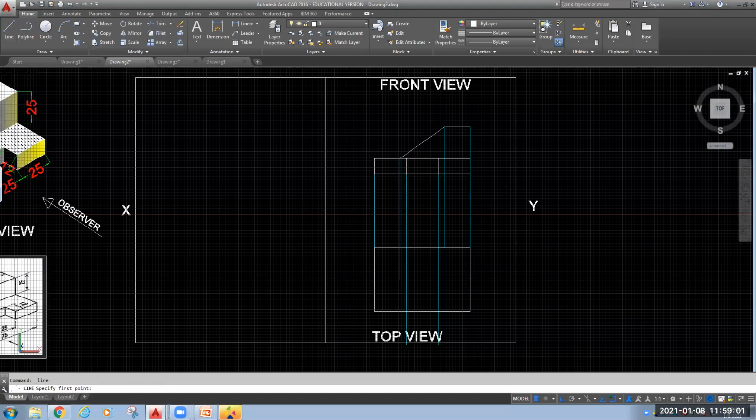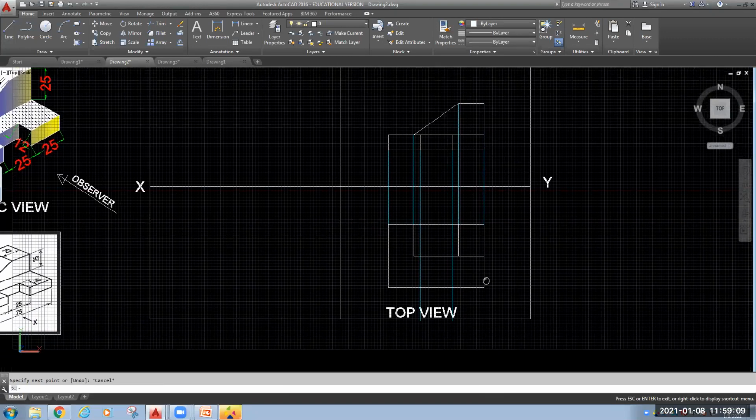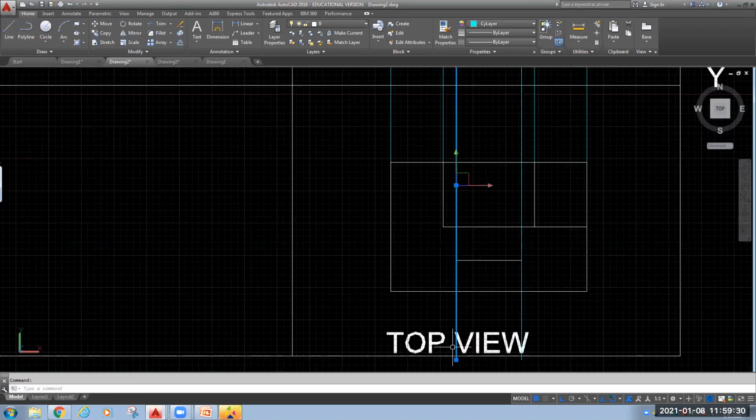Now we need to connect one line from here up to here, and I need to cut a slot. This cutting slot is there, na, of 12, depth is 12. So I need to draw a cut portion. On this side I need to move 12. This you can connect and here like this. Now the unwanted portion you can trim.